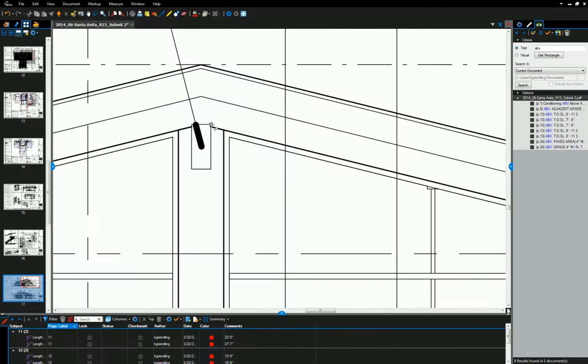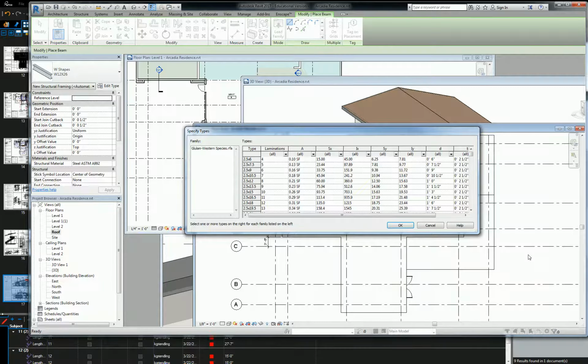So our beam is 1 foot by 5 inches, so 5 by 12. What kind of glue? Glue lam, Western Species. So anyway, guys, the size beam we want is a 5 by 12, and so you just scroll down this list to find the 5 by 12. We're going to have to go a little bit. 5.125, that's 5 1/8, by 12, right there.